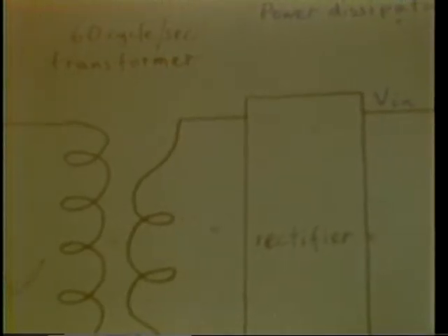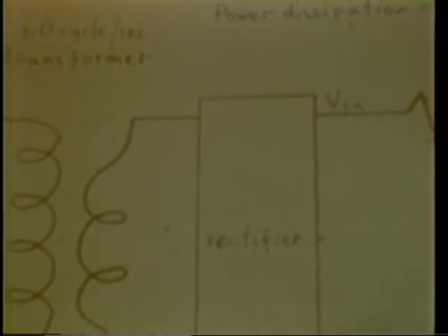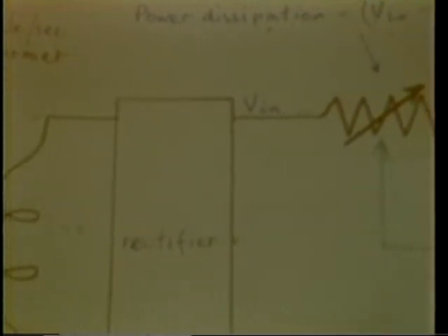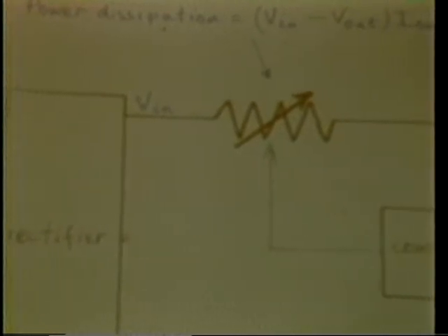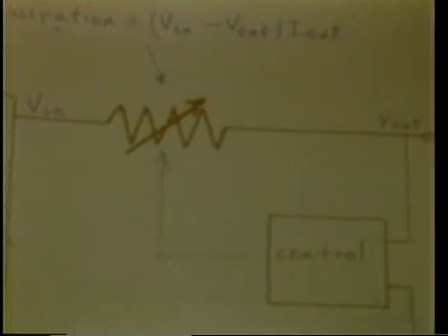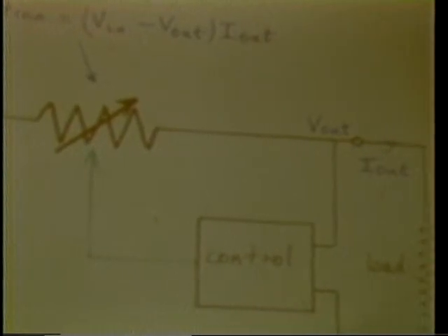Now, some of the things that you do with power processing circuits provide regulated power supplies, which is needed to power all of the equipment that we hear about. The conventional way of doing that used to be that you'd use a 60 hertz transformer to step down the input voltage to some low level, 6, 7, 8 volts, and then you rectify it to DC, and then you'd put in a so-called linear regulator to drop the voltage down to the required 5 volts or whatever, and that works perfectly well as long as you aren't transmitting very much power.